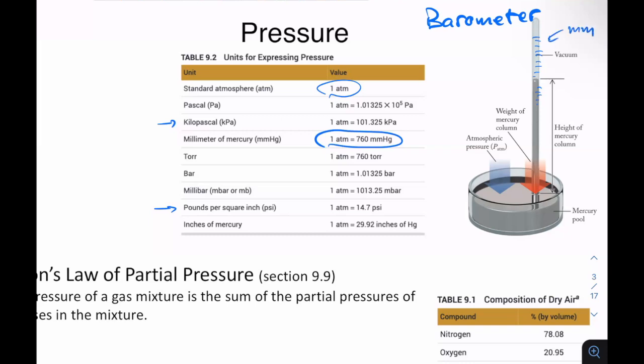And it's open at the bottom and it's closed at the top. Okay. And you've got a vacuum in here. But the rest of the pool is open to the atmosphere. So whatever that atmospheric pressure is that's pushing on the surface of the mercury, it's going to force that mercury up into the rod. And it's going to rise a certain distance before it's counterbalanced by the vacuum that's at the top of the tube.